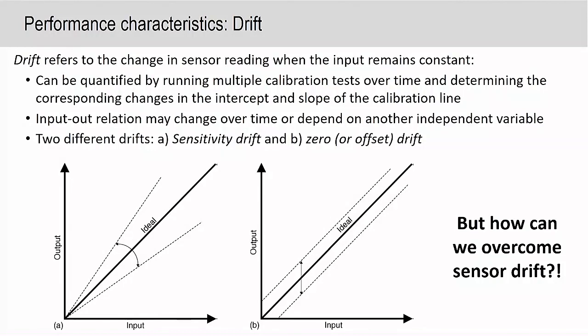then we put it into the body quickly. We measure the, say, pressure, the blood pressure, and then we can adjust the transfer function of the implantable sensor to match the one that we've just put in. And then we take that other one out because we know that other one's calibrated. So it's a real-time calibration. If you can get a known, calibrated pressure sensor into the same location short term, then you can use that to calibrate the sensor that's already there.